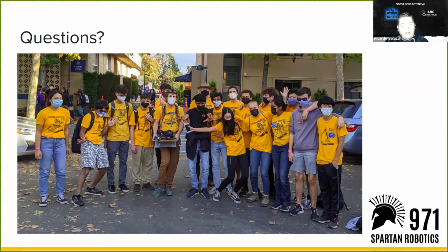Okay, another question, going back to the 5 cameras model you showed us of your robot, just as a confirmation, someone asks, all the processing for the 5 cameras is made in one Raspberry Pi, no, right? No, each camera had its own Pi. It's a great question. We wouldn't be able to do all of it on one Pi at that frame rate.